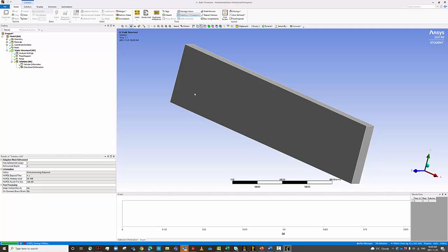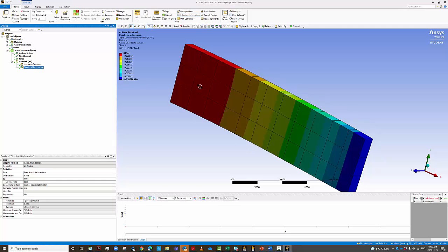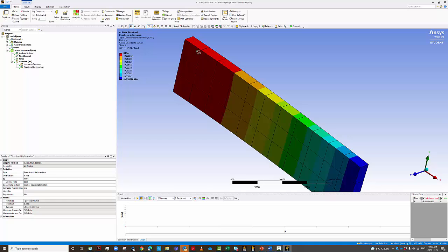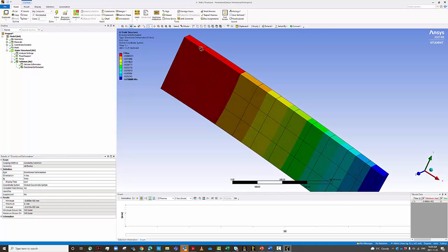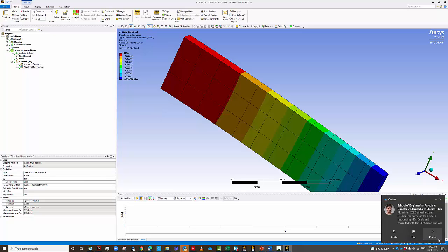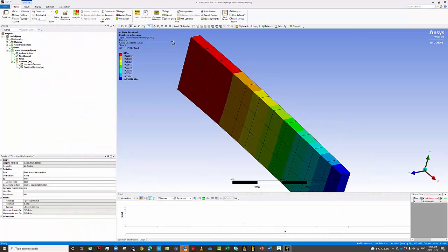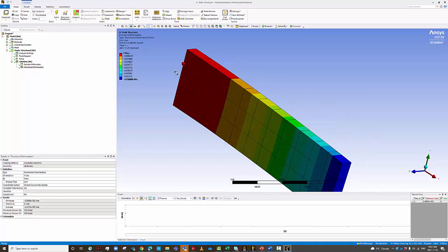It is still solving, as you can see. Solution is done. Directional solution, right? So of course you see here the most deflection is here because of the cantilever beam effect. You can see here that of course everything is in millimeter, and you can find the maximum value is minus 0.006541. Of course, again, you can just select the maximum, or you can see the deflection at one of the nodes or one of the elements, right? But let's assume that my criteria is this maximum. I just don't want this to be too long for you. I'm sure you will be able to figure it out.